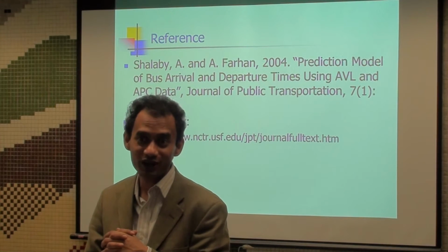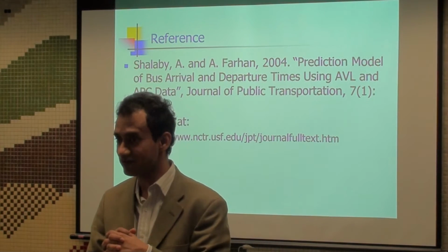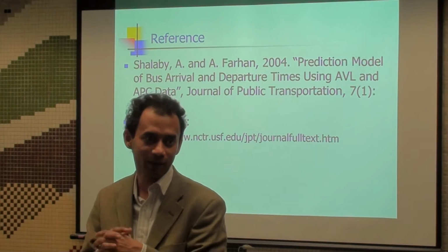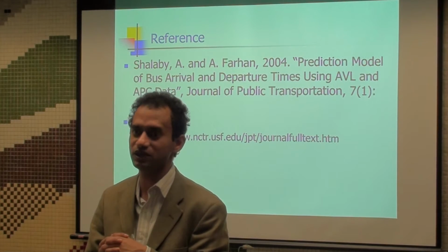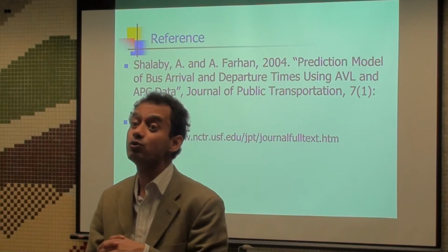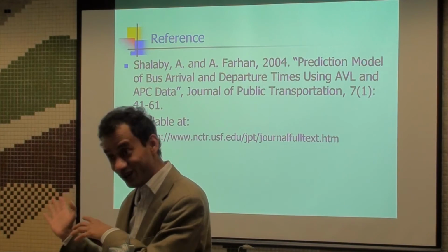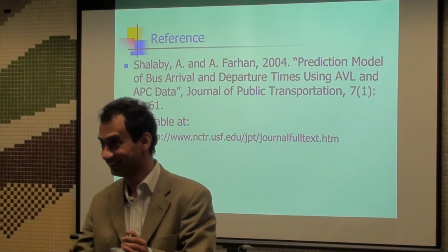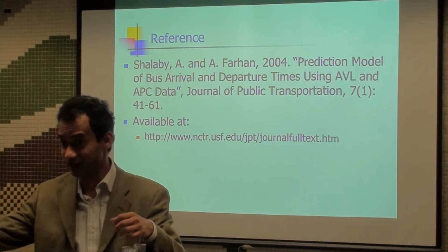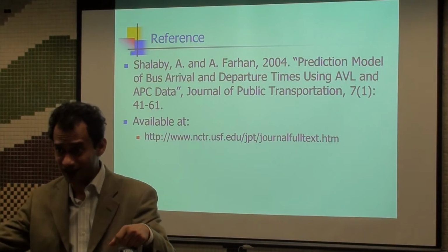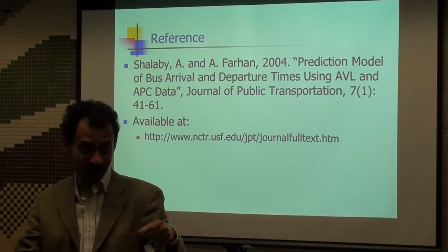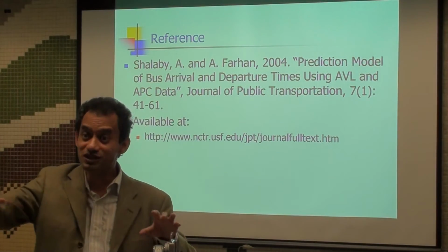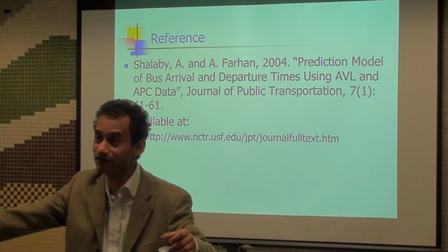So whenever we are talking about BRT, if we can't give exclusive right-of-way, we should be looking at technology-based active transit priority, TSP, transit signal priority, or we can also do a design solution. So this is one technology. You can also do the design solution, which is queue jumping. Like you have queue jumping at the intersection, like at the McDonald Bridge. You have seen that, right? There is a queue jumping lane for bus rapid transit, 159. So that means the bus comes and just comes in front of those vehicles.